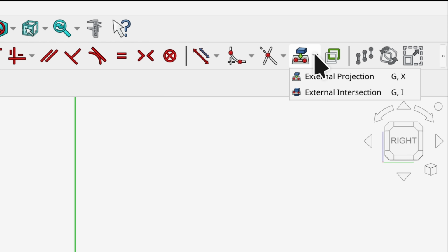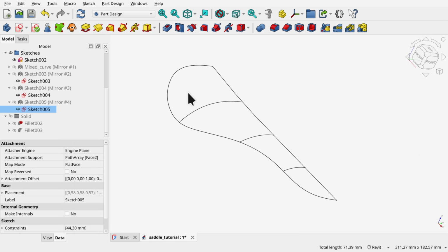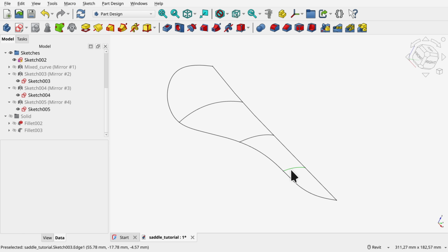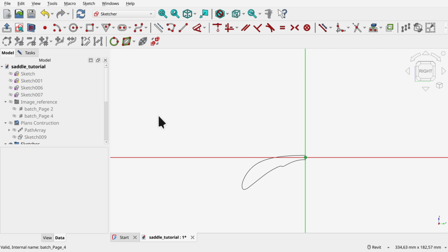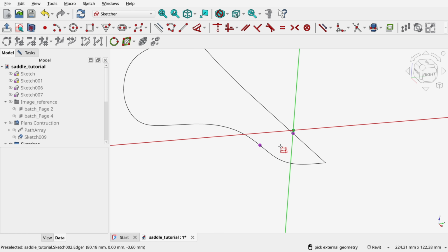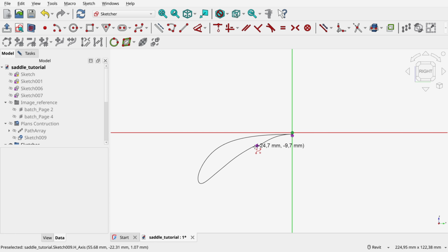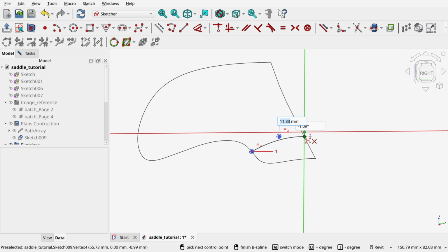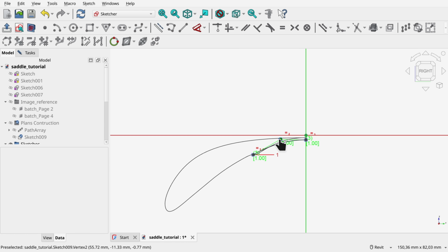They've also added the intersection tool, which is for me the most important addition in this update, especially if you want to do proper surfacing. In this bike saddle example, to build the surface, we need support geometry between the two boundary shapes. For that, we need the intersection between the sketch plane and those curves, so the support geometry can snap to them. With the intersection tool, you now just select the two shapes and instantly get the intersection points. You can then use these points to draw your support curve. This is really the tool I was missing the most for doing surfacing.